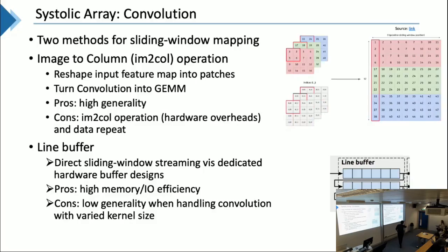If you look at this animation here, this is your convolutional kernel, and each kernel is 2 by 2, right? And you keep striding through different locations to get the corresponding weight matrices. The basic idea of im2col is, for example, in the first clock cycle, the data you want in the red map is 1, 2, 5, 6, and you just copy this in here.